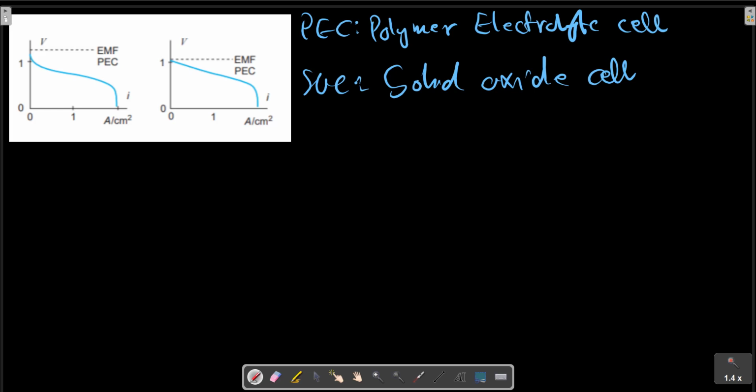This result resembles that of a heat engine with a heat exchanger of a given size. As the power output is increased, the higher heat transfer requires a larger temperature difference, which in turn lowers the temperature difference across the heat engine and causes it to operate with a lower efficiency.